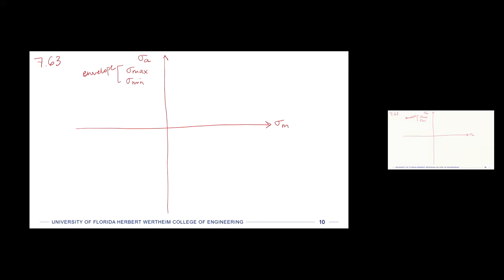So we can start with some anchoring magnitudes on here. At the top of sigma A, and this is actually the top of both of these axes, we're going to have the ultimate strength, sigma UT. Nothing can go above that stress. And if this is a 1-to-1, I can draw that on the x-axis as well and label it. So that's our ultimate tensile strength.